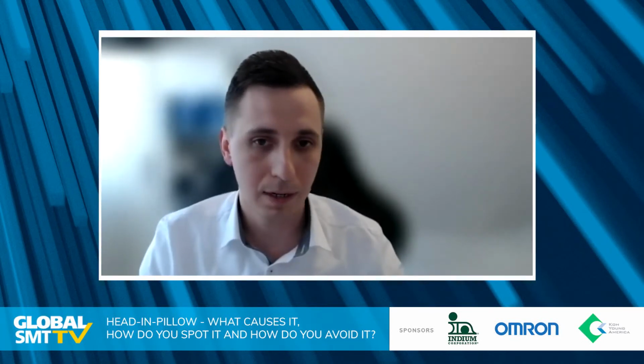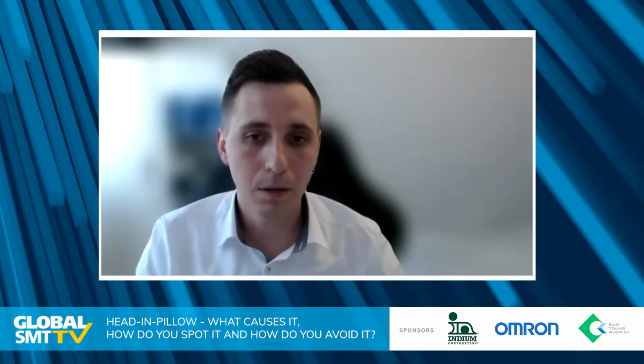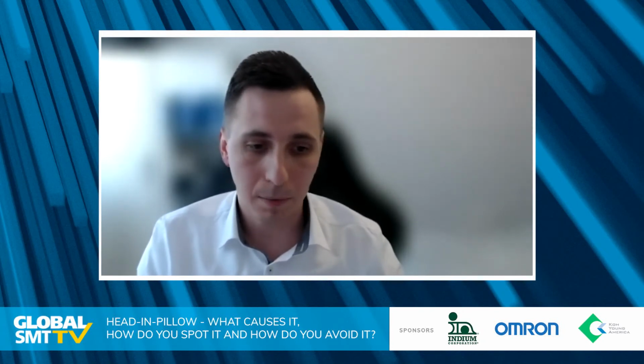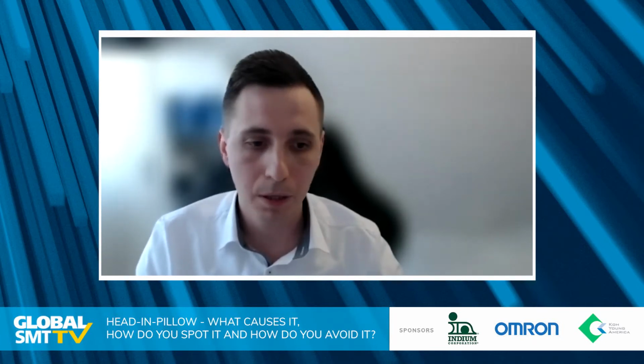Piotr, does the reflow temperature have an effect on the defect? Yes, I think if we are looking at the process, the reflow has the biggest impact, and it can improve or reduce the head and pillow problem. Higher temperature and longer exposure to the temperature can increase the risk of head and pillow.